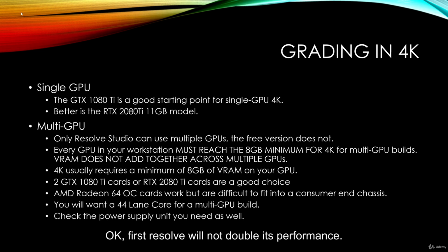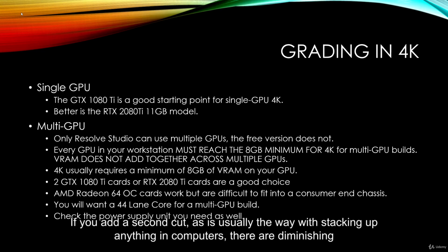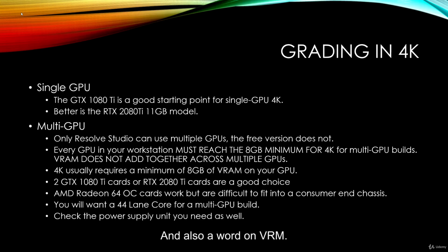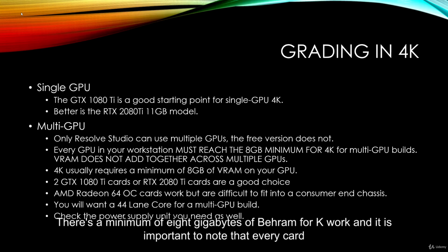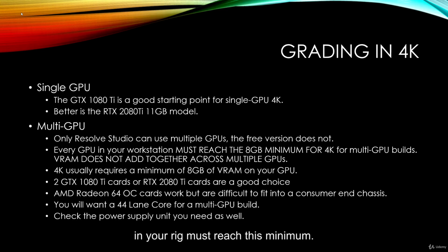Okay? First, Resolve will not double its performance if you add a second card. As is usually the way with stacking up anything in computers, there are diminishing returns. And also a word on VRAM. There's a minimum of 8GB of VRAM for 4K work, and it is important to note that every card in your rig must reach this minimum.